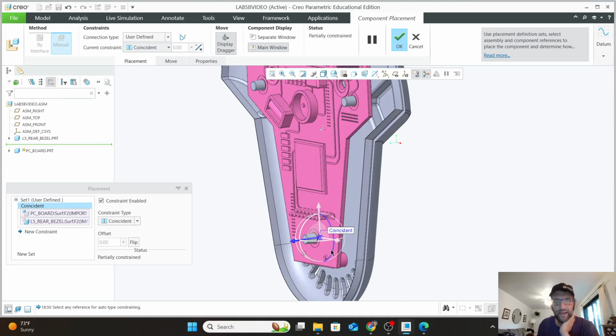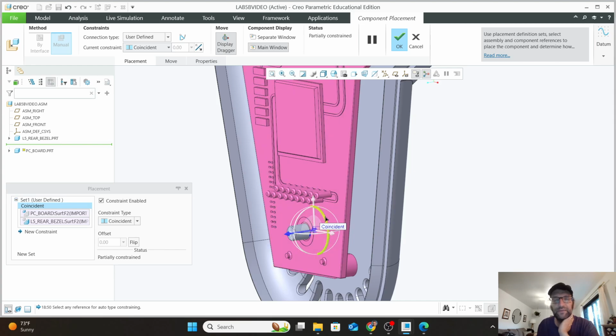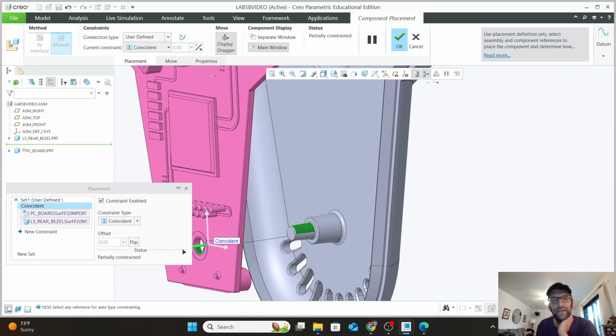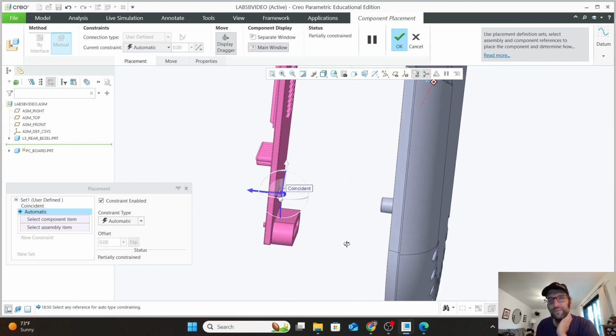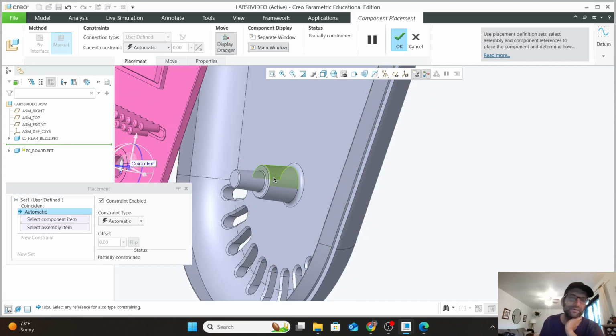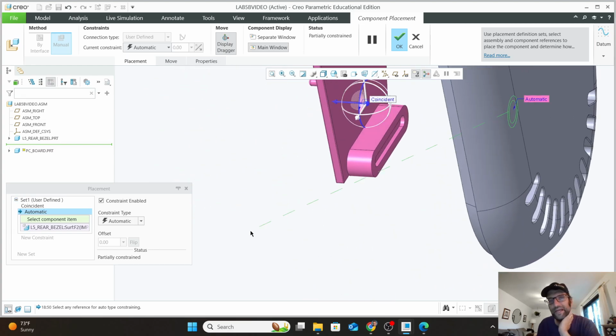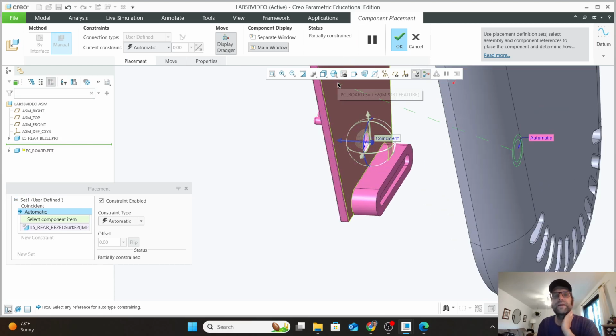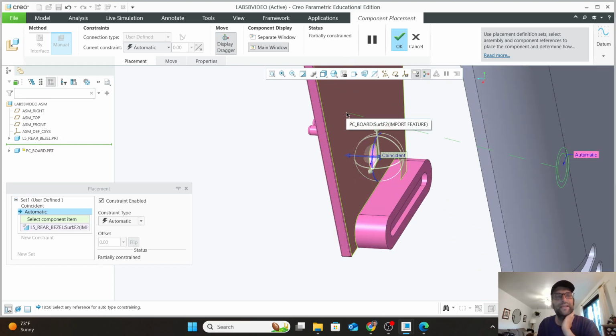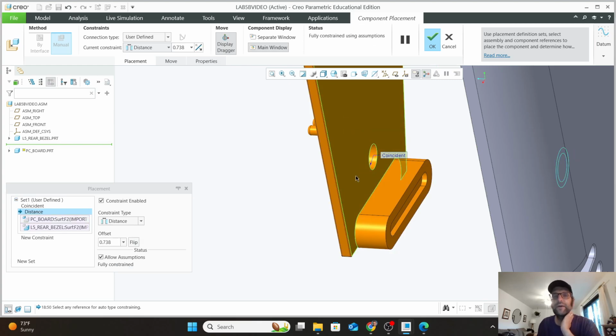And we look at our degrees of freedom here. We still have 2 remaining. And we want to go ahead and eliminate those. So let's add a new constraint to this. And remember with this one, unlike the last one, we're not looking to do a motion study here because this is an assembly where the things are attached to each other and should stay that way. So we're not going to worry about changing that setting to go ahead and allow that motion.